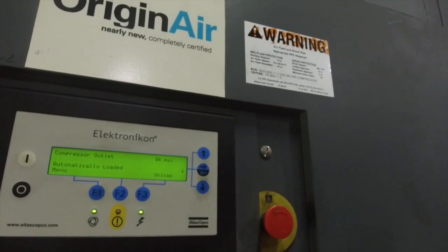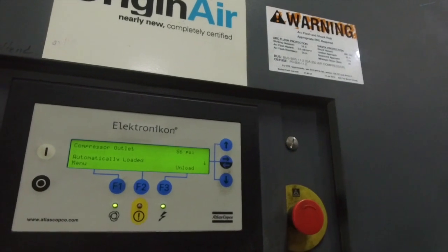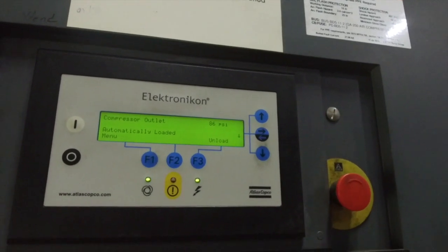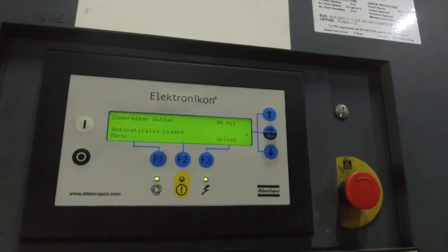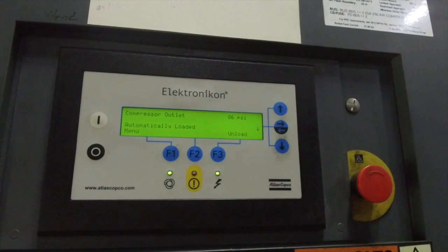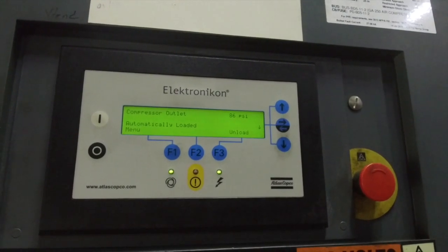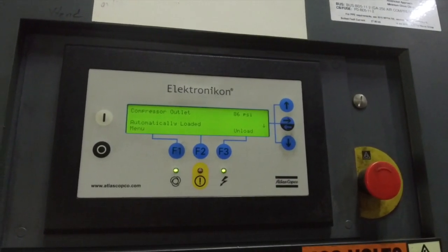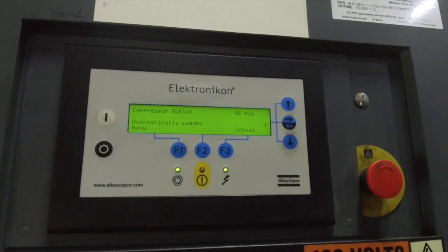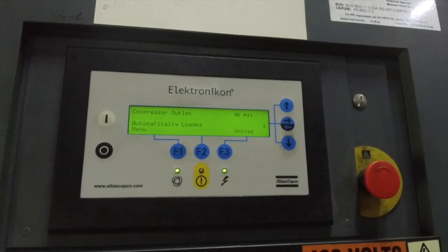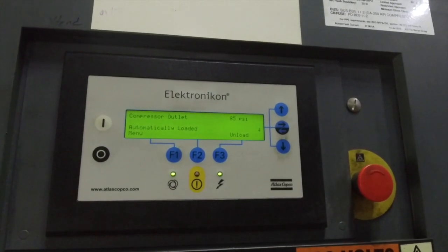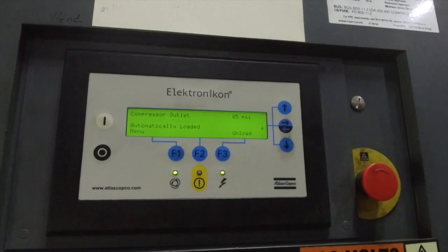And the remaining 15% goes to artificial demand, which is a little hard to understand, so I'll give you an example. Say, like in the previous graph, you're not getting enough compressed air in your system. You only need 85 pounds per square inch, but the system is set to 100 pounds. Well, guess what's going to happen now? All of your leaks and inappropriate uses are going to have extra large flow rates. Artificial demand is the extra loss associated with having pressure that is higher than necessary.